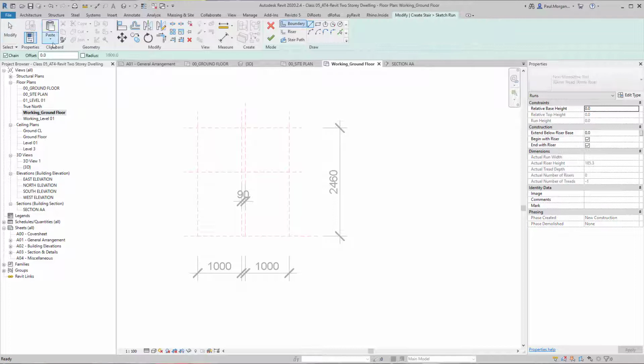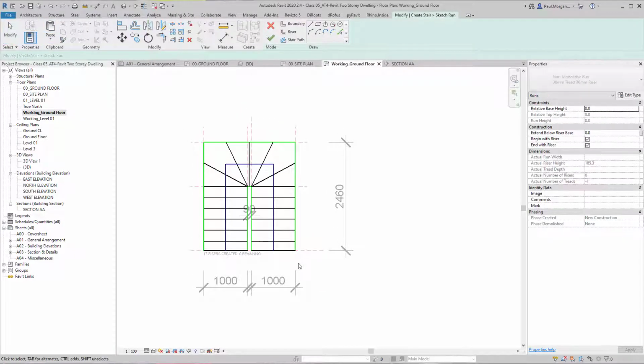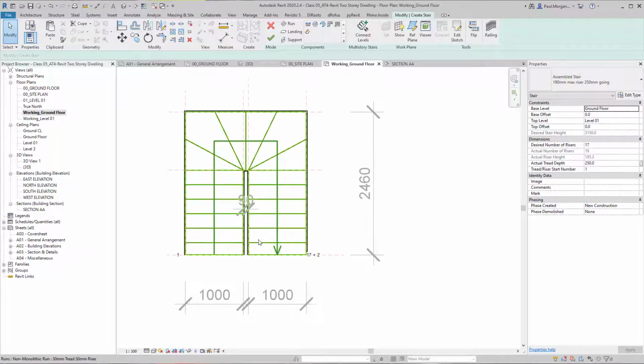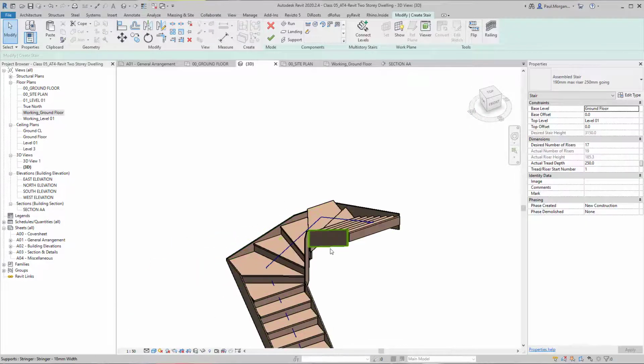Go sketch, and let's just see if I can paste. So I copied that first, I selected everything, went Control C, then went back into the sketch, went to the modify panel, and then came over to paste, and then go align to current view. There we go, nice, that saves us a bit of time. And then we'll say OK. There we go, that looks good. So let's go back to our 3D view. Nice, excellent, that's good.